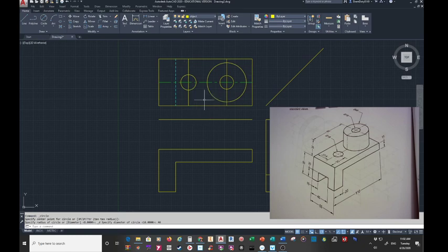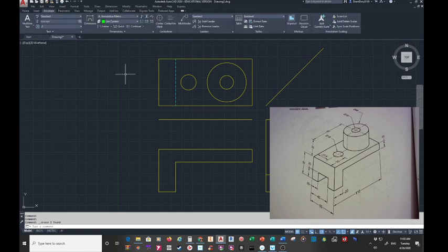So now that I've got that drawn on there, I'm going to get rid of these, because there's another way of doing our center marks and center lines that I want to show you that we're going to use. While we're talking about that, let's just go here. I'm going to go ahead and put them on the right layer, which is center, and you go to annotate. Notice you have these lovely two little things here. One's called center mark.